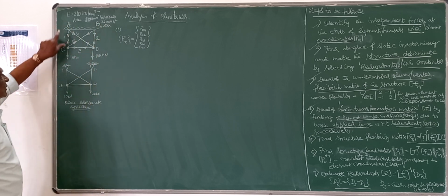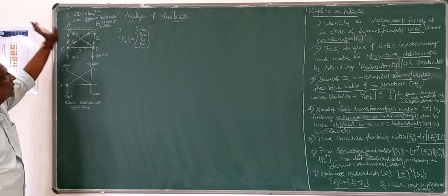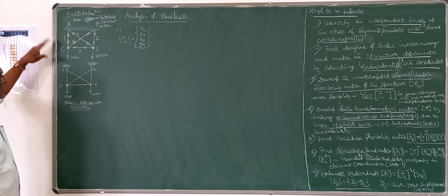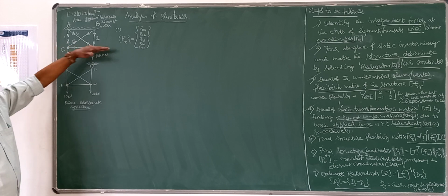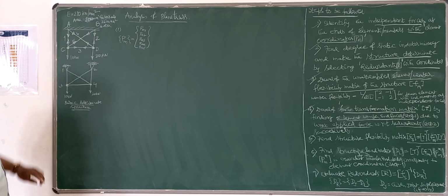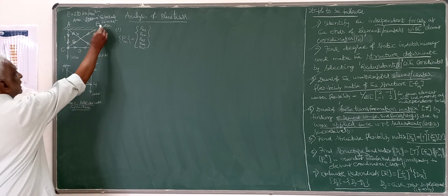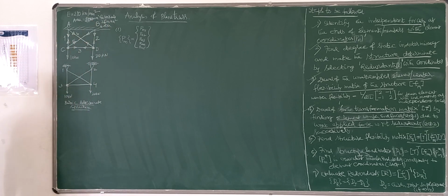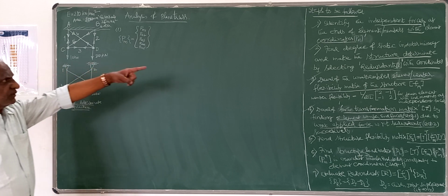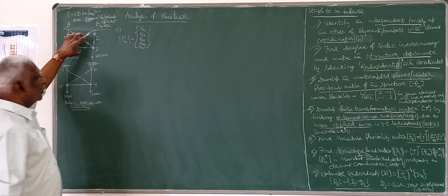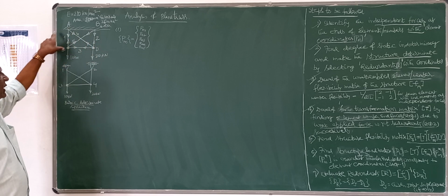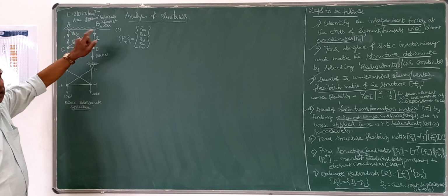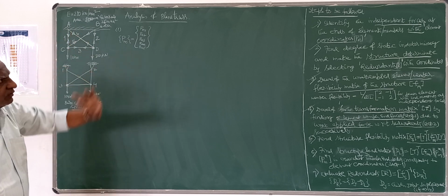So that means area of cross section for members 1 and 2, you can take 2000 millimeter square, and for all other members, that is inclined members 4 and 5, and horizontal member 3, you can take area of cross section as 600 millimeters. But that data was missing, so that also you can take it here. So that is the first step. I have to identify the element coordinates that I have identified here. Element coordinates are only one coordinate per member, that's only the axial force.